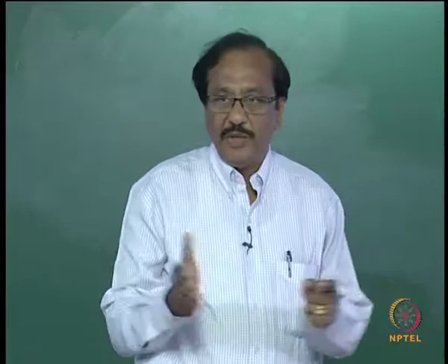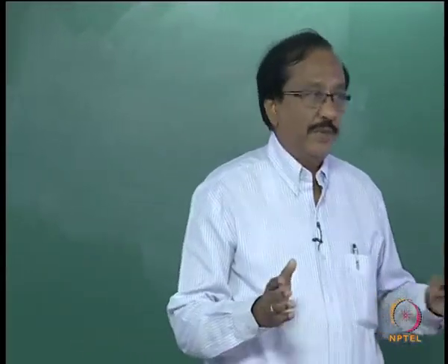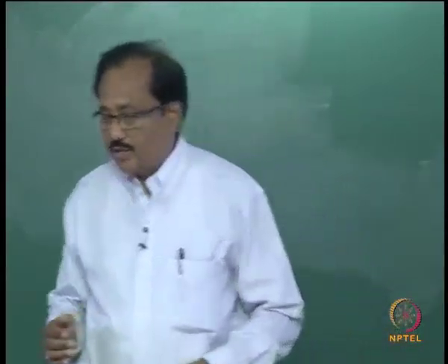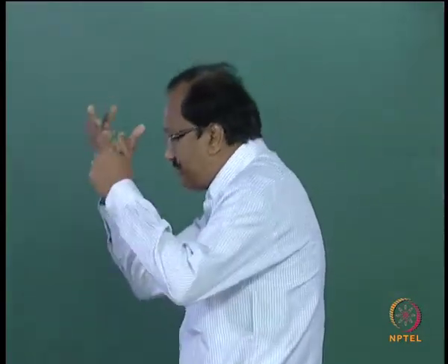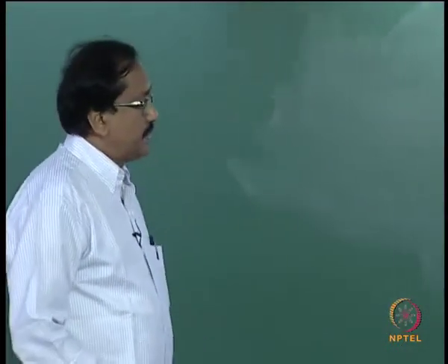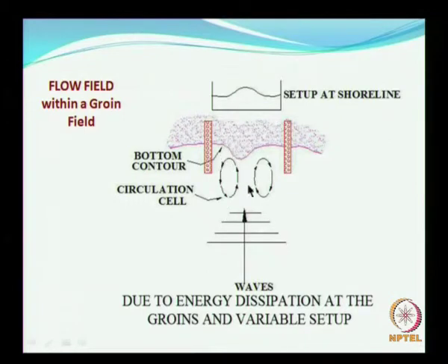So the spacing between the groins is also very important in order to make sure that it is effectively retaining the sand in between the compartments. So you can have something like this, you can have two circulations as shown here, and you can have a hump or advancement of the shoreline somewhere in between the two groins.